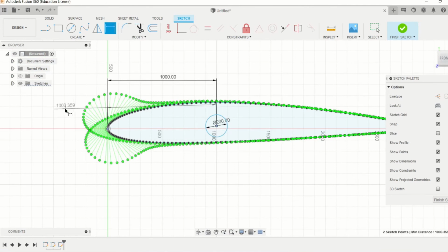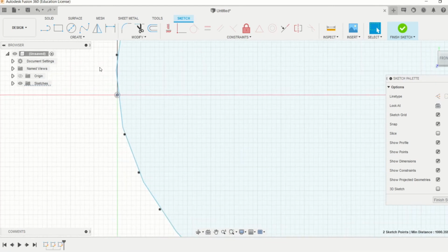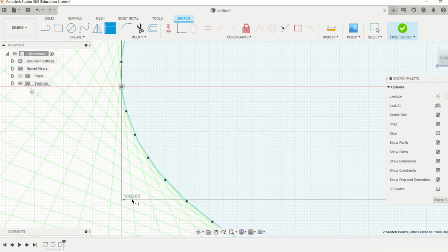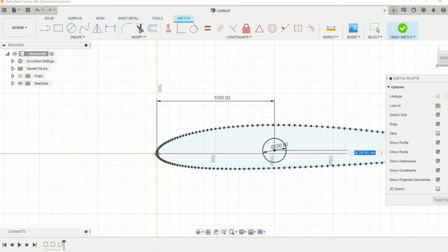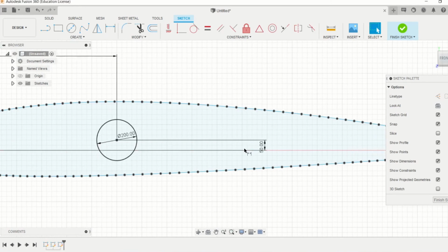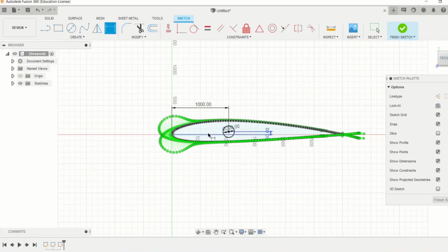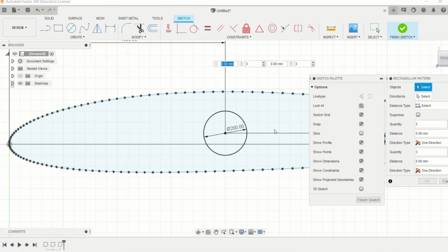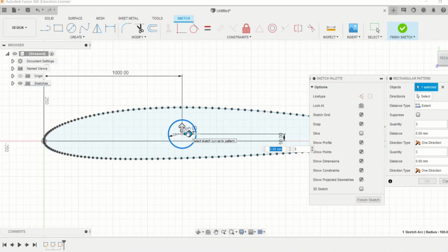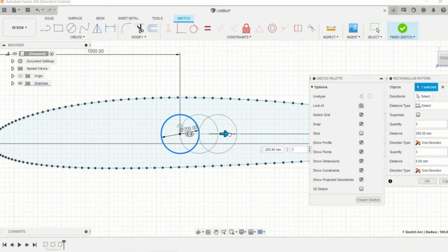Also make sure that you always have the right point. Okay, so once you have the height, let's just say 50 from the quarter line, and let's now make a rectangular pattern. Let's say I want to have 3 of these. So just select it using the rectangular pattern. It has a quantity of 3 selected, and now you can just move it until you have the specified distance between the 2 center points. In this case 575. Let's say we want about 700.